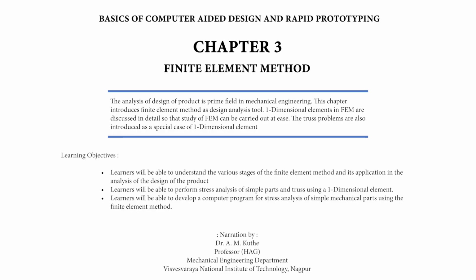Truss. The problem of trusses, that is finding stresses induced in the truss members, can be solved using the finite element method. The truss is discretized into elements and nodes by considering a truss member as the element and a joint as the node. The truss shown in figure 3.14 is discretized into 7 elements and 5 nodes. As the force on the truss is always applied at the joints, that is nodes, the finite element method can be used. The element is considered to be a one-dimensional element.